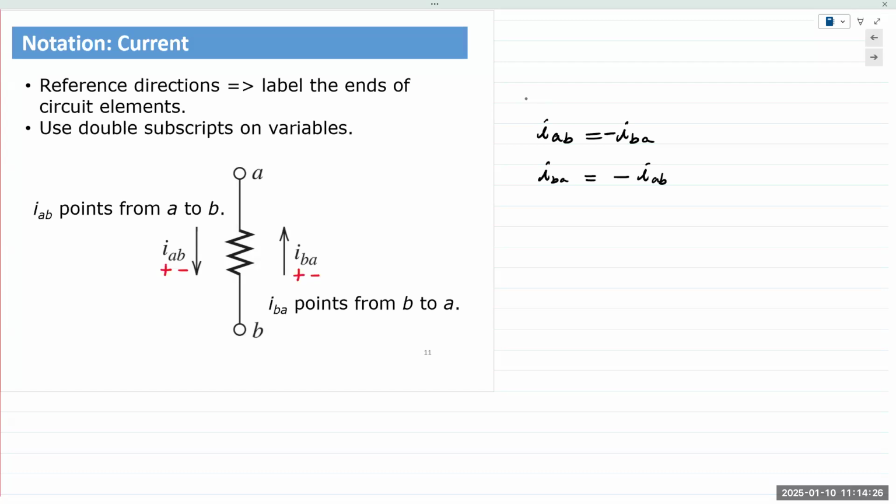So then logic dictates that if you have one source in a circuit and a resistor or an element connected directly to that source, then the current direction will follow the current coming from the source. You may assume any direction you want, even if it seems counterintuitive.